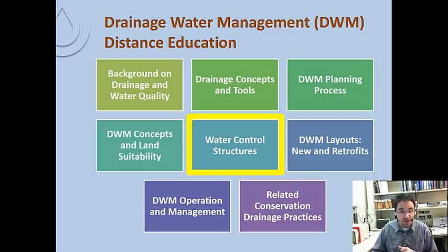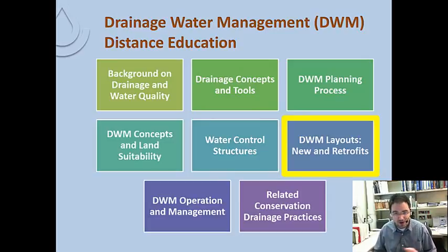Then drainage water management layouts, new and retrofits, and so this is where you get to think about how we design that system maybe differently than we would if we were just thinking about conventional drainage, and how might we retrofit that. So Dr. Gary Sands is developing a module on facilitating drainage water management, making sure there's no negative impacts on surrounding neighbors, and thinking about how we design and lay out the drainage system to facilitate drainage water management.